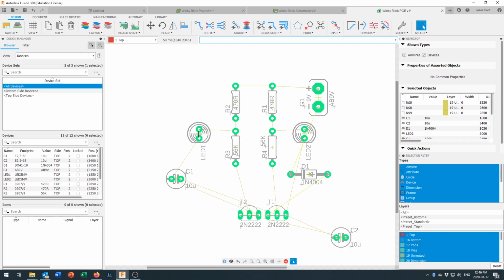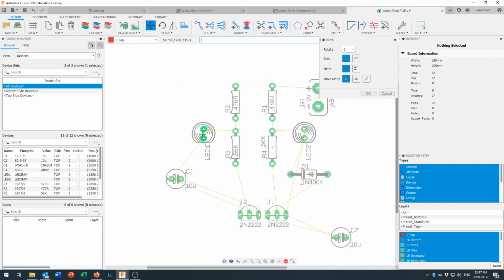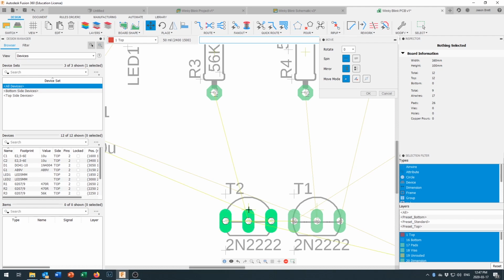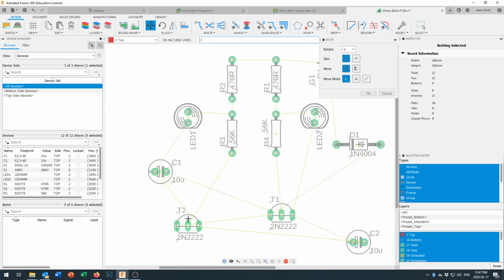And here we go. We're going to move this. Let's pick up move. And for right now, I'm just going to pop that in right there. Pop that in right there. You know, have a little bit of symmetry. The diode is actually only going to connect over here, so we can pop that off to the side for right now. And our transistors, oh, I got a little warning beep. You may have gotten them already because I didn't click on the crosshair. You have to click right on that crosshair to move the transistors or move any of the parts where you want to move them to.